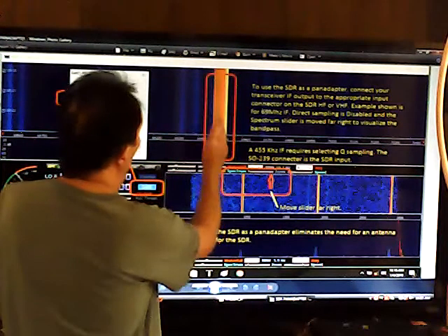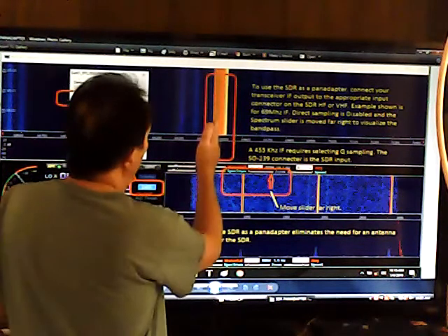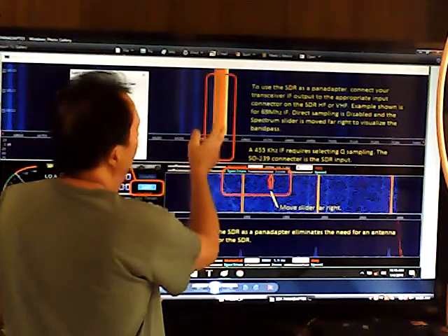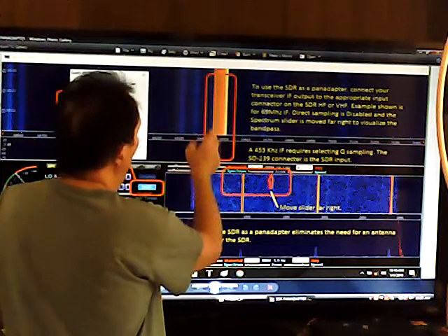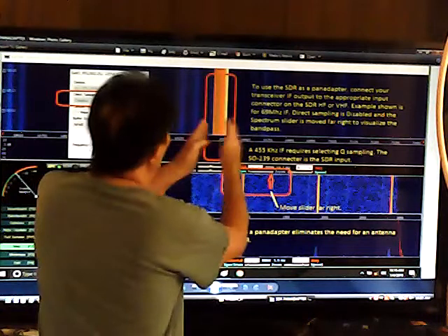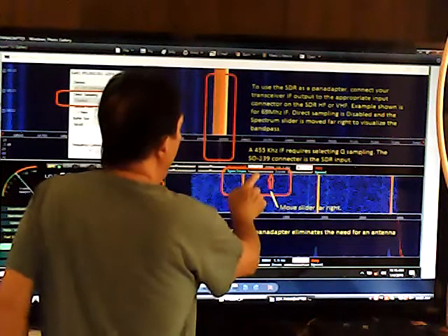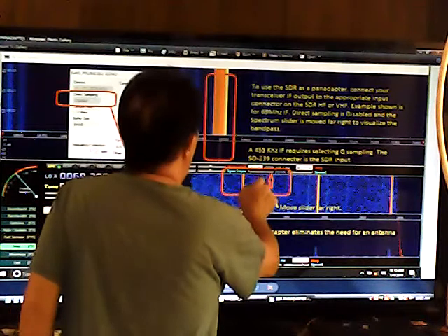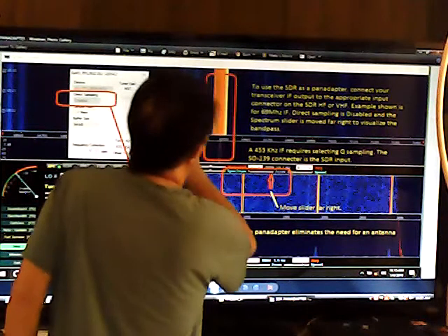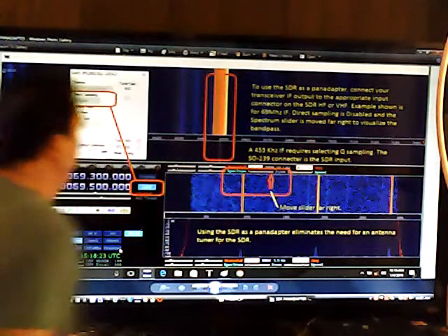That is basically the whole band. Say you're looking at 7, for a 40 meter signal, 7.20 megahertz. Everything in that spectrum is compressed down into that IF strip. By adjusting the spectrum display here, you are going to broaden that out so you see the entire spectrum.